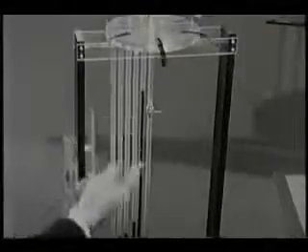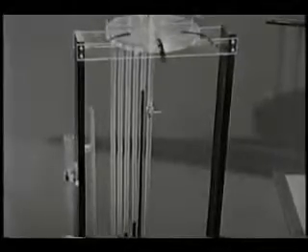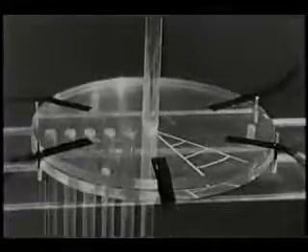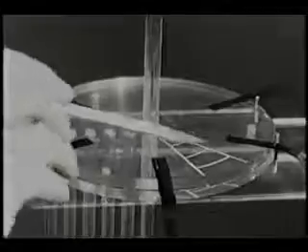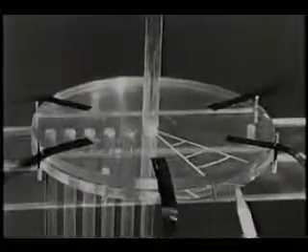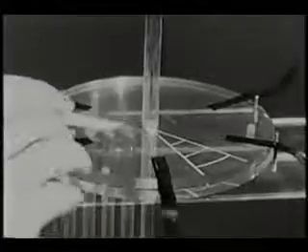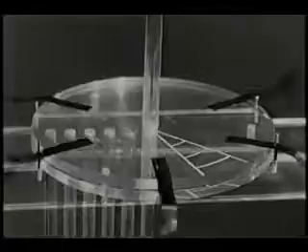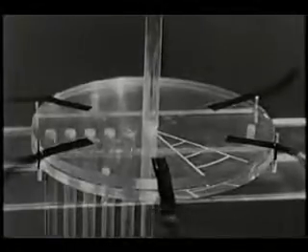The reason for this is that the through-flow cross-sectional area between the disks increases with radius. This area increase causes a fluid deceleration, and by Bernoulli's integral, a pressure rise. Actually, the viscous forces in the narrow gap are by no means negligible.